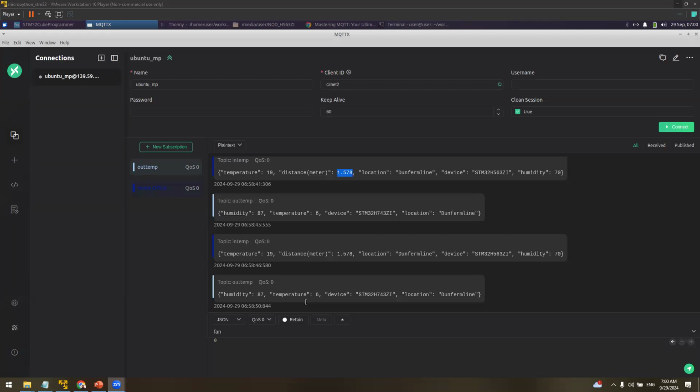For example, if you see the number of GPIOs provided, we get almost 240 IOs from the STM32. It has a lot of inbuilt peripherals, like it provides me 16 timers. The speed is very high, like 480 megahertz. So this makes STM32 much more superior than ESP32.